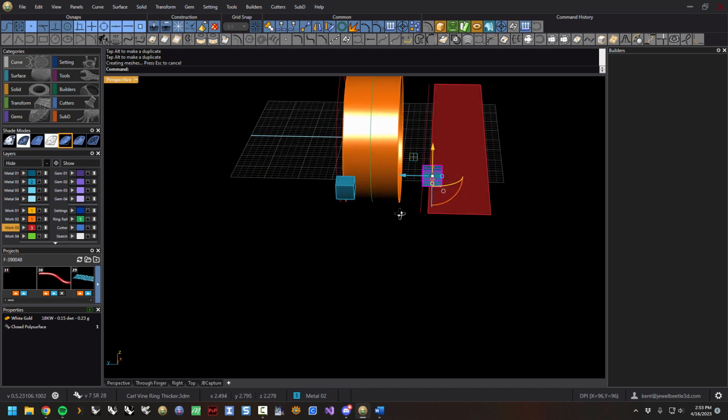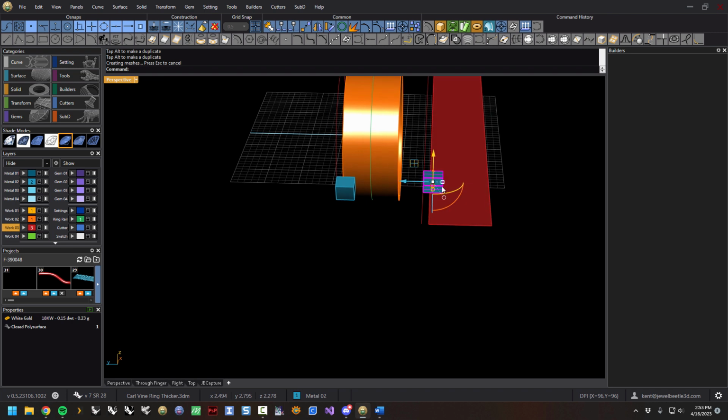And the reason we do that is that the further away from this surface that you get, the more chance of distortion that there is in the model. Okay. Plus, if you have a busy drawing, you may not want everything on the drawing going up on the flow. So you might want a tighter boundary as far as that goes.